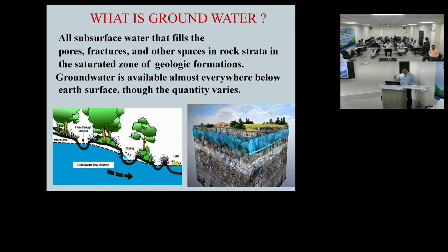So ultimately, in a hilly area, suppose in Meghalaya, the gneissic terrain, where will the water flow? Because water needs storage spaces also. Flowing from a gradient, it will come as storage, and those storage spaces in a hard rock are called fractures. Those fractures are actually planes of weakness. So when you go for a well in a hard rock area, we need to see if there are lineaments. Lineaments mean planes of weakness. You can easily find them.